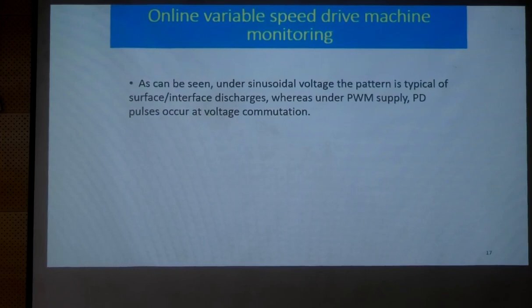So these are the various types of discharges that usually occur. If the discharges occur internally, it is like internal discharges. If there are any manufacturing defects, like some voids or cavities, you have designed for a particular voltage level. Due to these switching aspects, that cannot be withstood, and at those cavities, it is an air medium when compared to the other insulation medium.